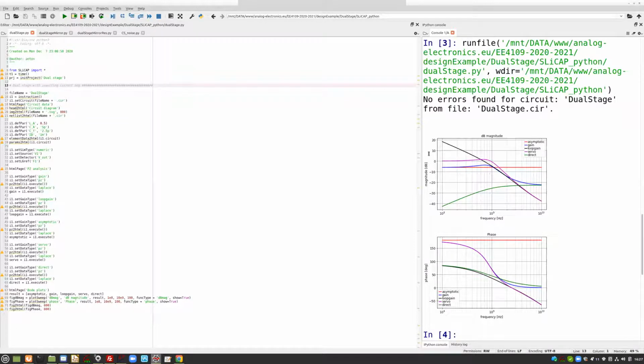And the black one is the loop gain. And you see the loop gain stops at about 1 gigahertz. So it appears that the bandwidth is large enough. The loop gain pole product, it appears to me like a second order system, two dominant poles, because I see a slope here like two dominant poles.